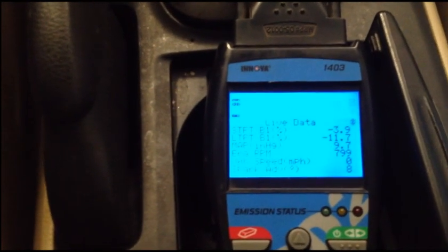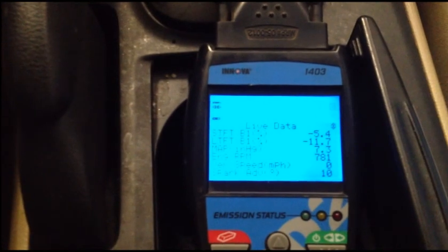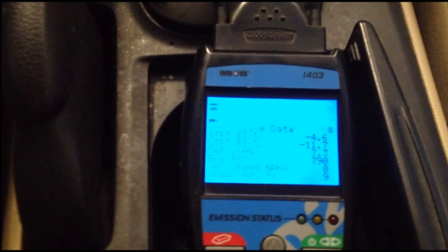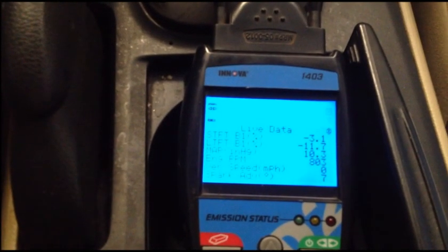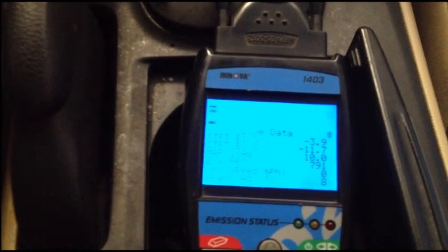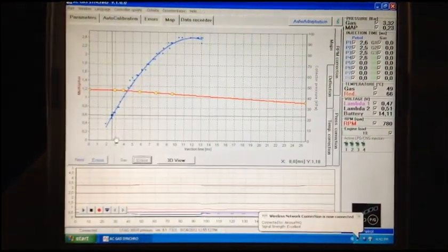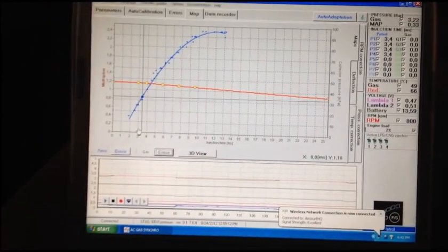trim. And this will just give you another way of seeing what's going on, because you want that value to be identical to what it's doing whenever it's on CNG, and you can make corrections on the fuel map. And it's basically doing that already through those two charts that we're going to see up here. It's essentially doing the same thing, but you have more of a direct readout through looking at your short-term and long-term fuel trims there.